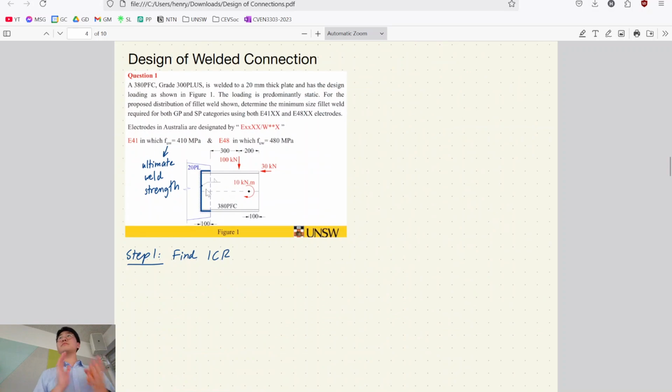Isn't welding stronger? Yeah, it's not like they don't weld. If it's done in a factory and can be prefabricated, that's actually good, because then the welder does a bunch of different jobs in the factory. Or sometimes if it's mass-produced, they have a machine weld it, and it's very precise. But on site, it's the Wild West. Welding is very hard, because if you're welding something 6 meters long, there's a good chance you're going to mess it up. Welding is very strong though.